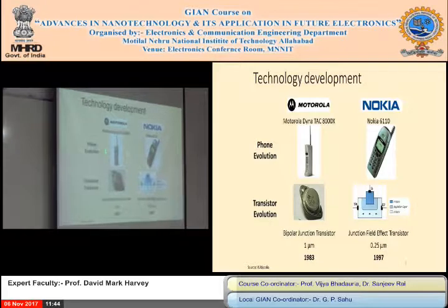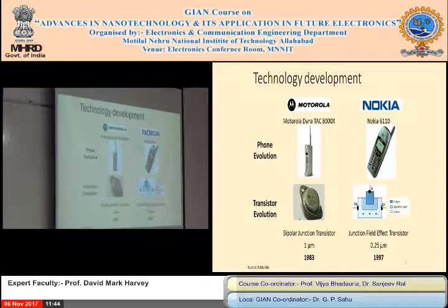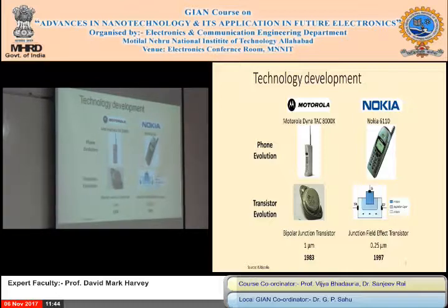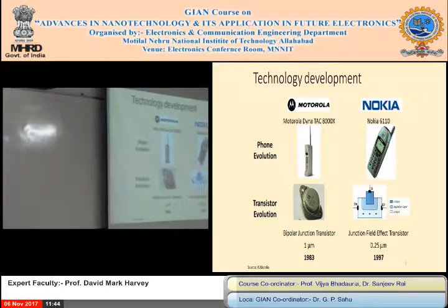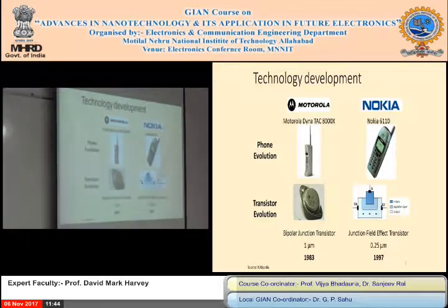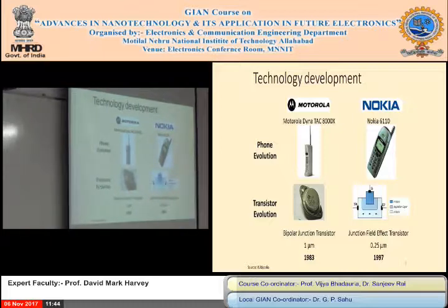And you see how big it is. The transistor in that generation was the bipolar junction transistor. And the size of a junction, the size of a transistor, as we'll see this week, is very important. Small isn't necessarily better, okay? People will tell you that. What you want to do with a transistor is use the transistor that will do the job for engineers. So transistors then are about 1 micron, that's measuring across the junction. Sometimes they call it a line width later on when it gets to silicon technology. But 1 micron is quite small.